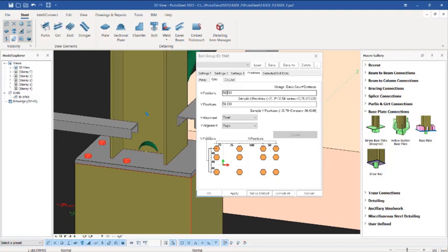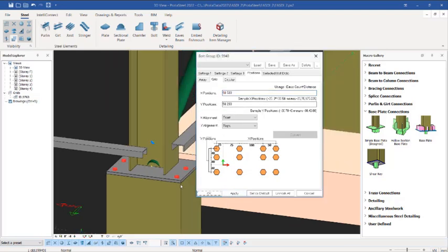For the 200 in the X direction, mind you, you have to know the difference between the X direction and the Y direction. Here is the X direction, shown by this green icon there. So we'll make it 350 in that direction. Click on apply. You can see this one going this way, so you have to shift it again, make it 500. Make sure you have a space here. Click, so I think this is fine now.